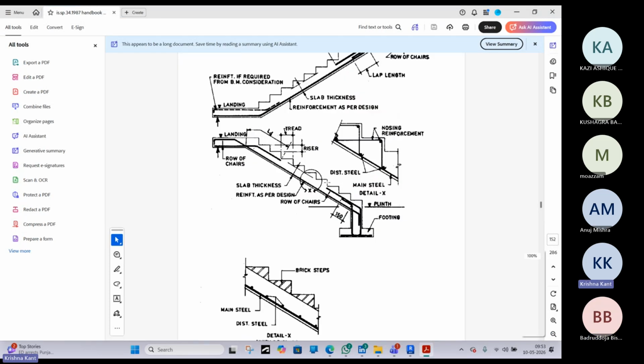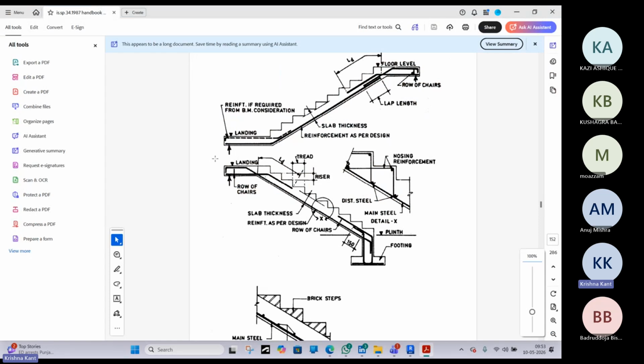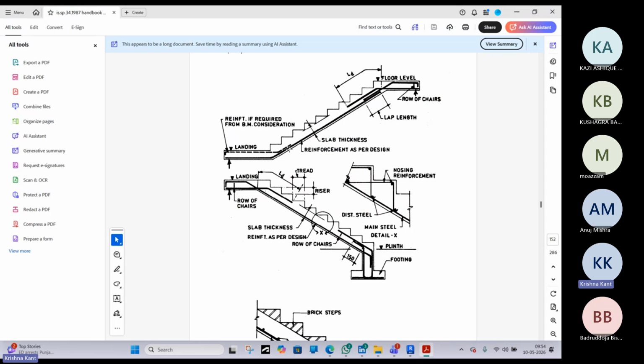So what you can notice in the stairs detail, on the bottom, if we are not having any slab, bottom floor, either we need a beam, so that the load will be carried through the beam, or we will have a certain slab, because in a slab we can provide the rebar in this direction.